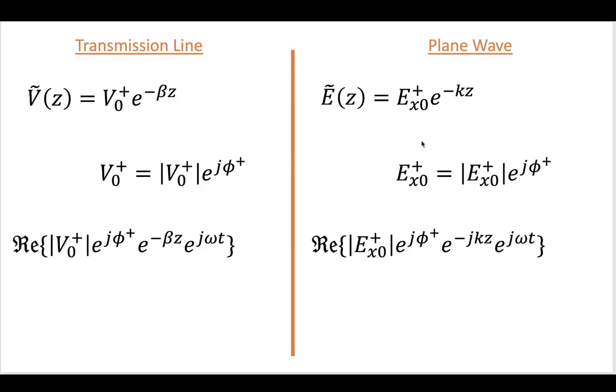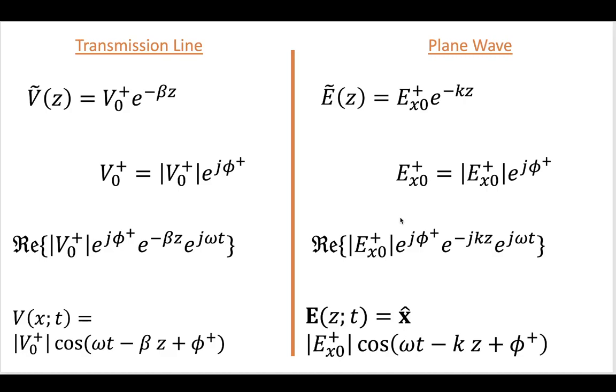Now, doing that makes a lot of sense, because this once again helps us to go back and forth between phasor, and this is a phasor, I've denoted this with a tilde, to the instantaneous form. We can see that these parts are all j to the something, so they're going to be inside of the cosine term. And likewise for the plane wave, we see the same thing. And the coefficient is not a function of z, and so it's not going to be getting smaller as z changes. And this is because we're dealing with the lossless case.